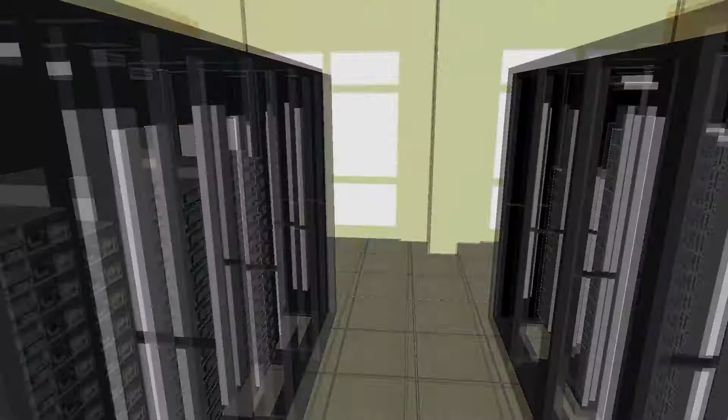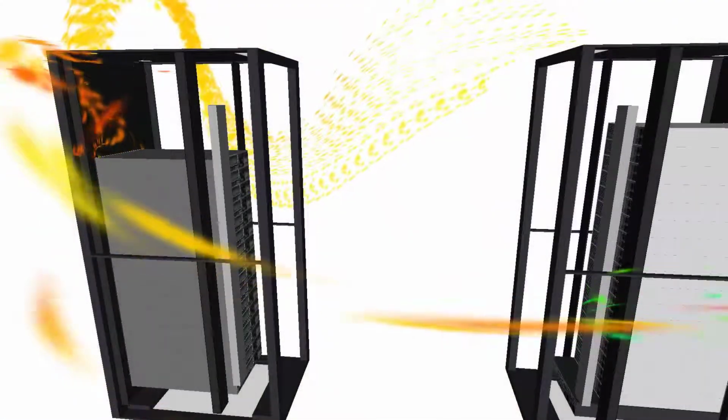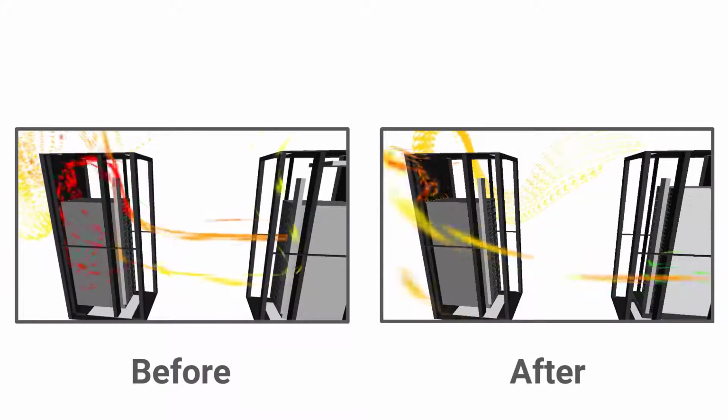It solved the local availability problem and saved capacity for use in the future. And this can be seen clearly by comparing before and after. This configuration meets availability and decreases capacity resource utilization by 16%. And it also reduces chilled water system energy consumption by 5%.